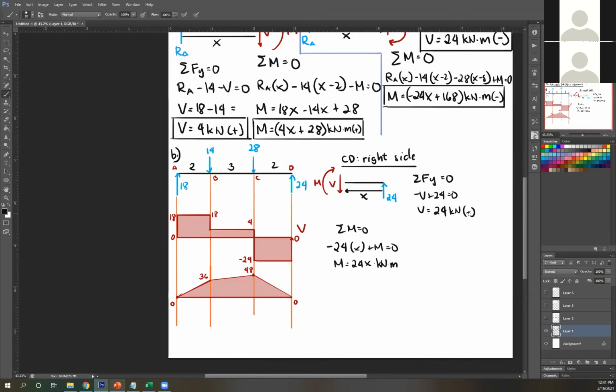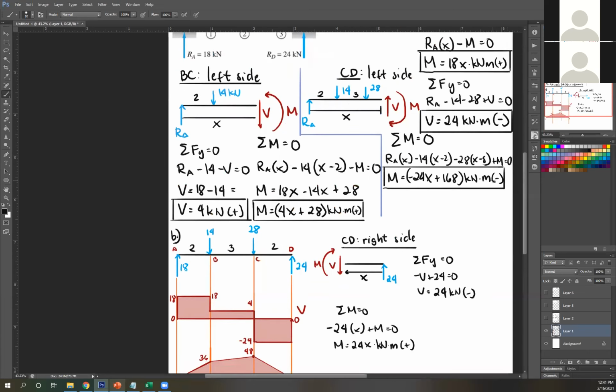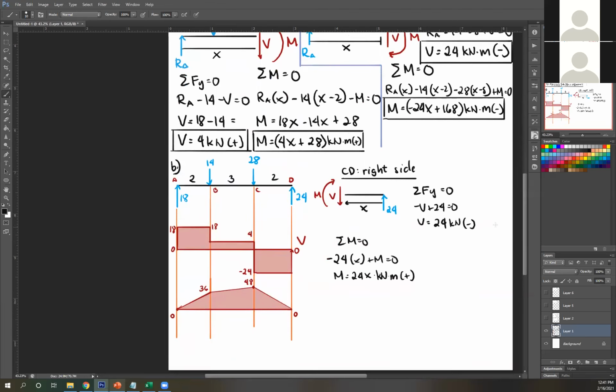Positive, therefore correct assumption, and to get the sign, okay, so your moment is going to hit here, it's going to bend this way, so it's a happy face, therefore positive. So why is it like that? Here our moment is negative, here it's positive. Well, that's because you took it from a different end. You took this from the right side. So let's see. If you start at the right side, again, because this is the right side, you start at 0. Positive, therefore upward slope, meaning this way. Okay, that's your upward. Downward would be this way. So upward slope. And then by how much? It's 24 times x. And here our x is 2. 24 times 2, that's 48.